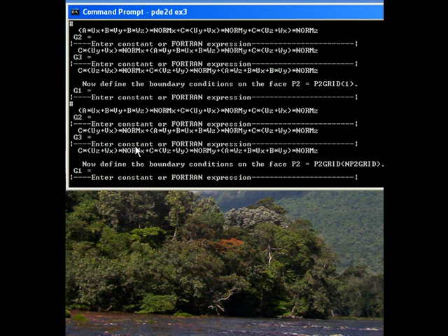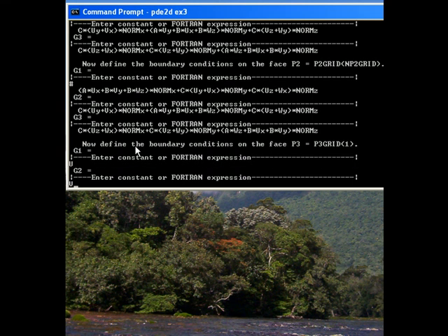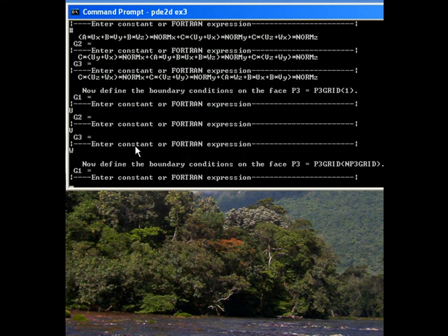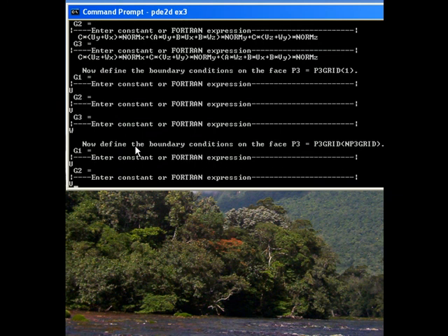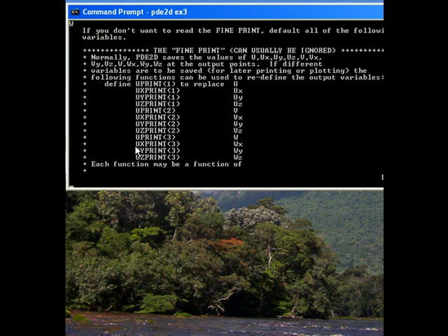So I put those in the same way. And the top, same thing. Now P3 equals 0. That's the right. That's where it touches the boundary. So U, V, and W need to be 0. That's where it touches the floor. And P3 equals pi. Also U, V, and W equals 0. That's the other leg of the arch.